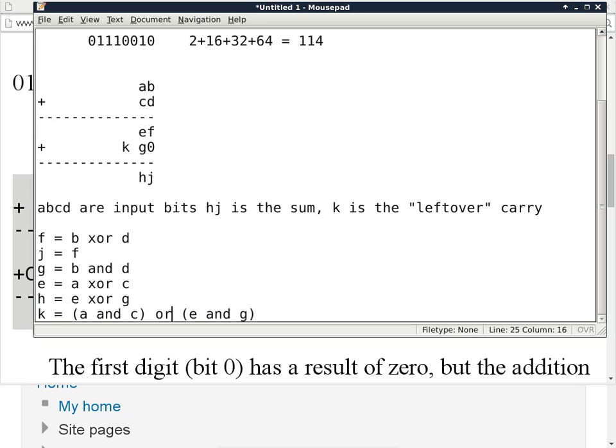Yep. How do you draw exclusive OR? What's the symbol for that? The symbol of exclusive OR is a plus with a circle around it. Sure. Okay, here's a quick quiz. In C, as a bitwise operator, how do you specify exclusive OR? The caret. A caret, that's right. So in C, it is a caret, which most people think is to the power of, which obviously does not work out.